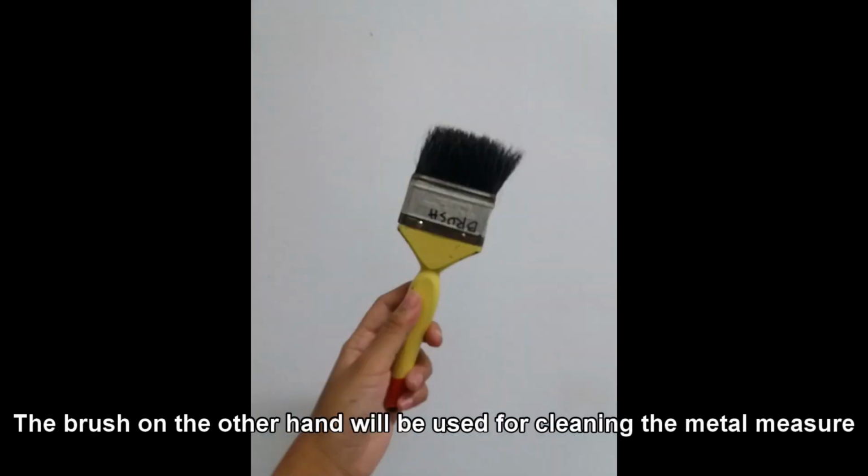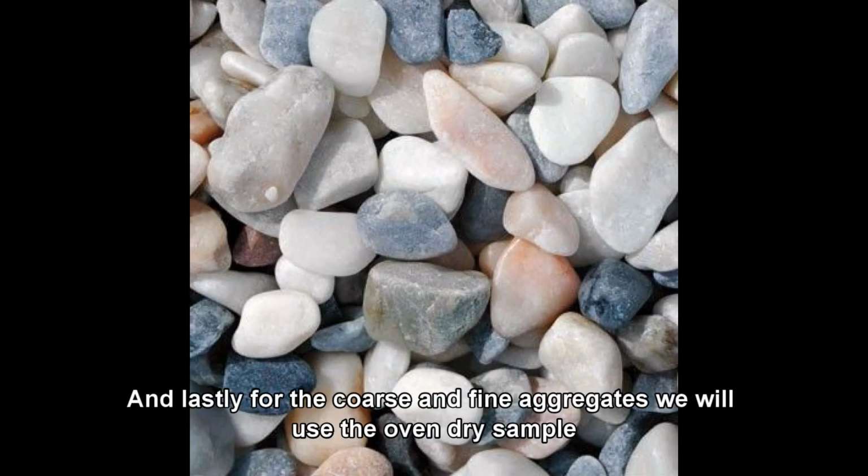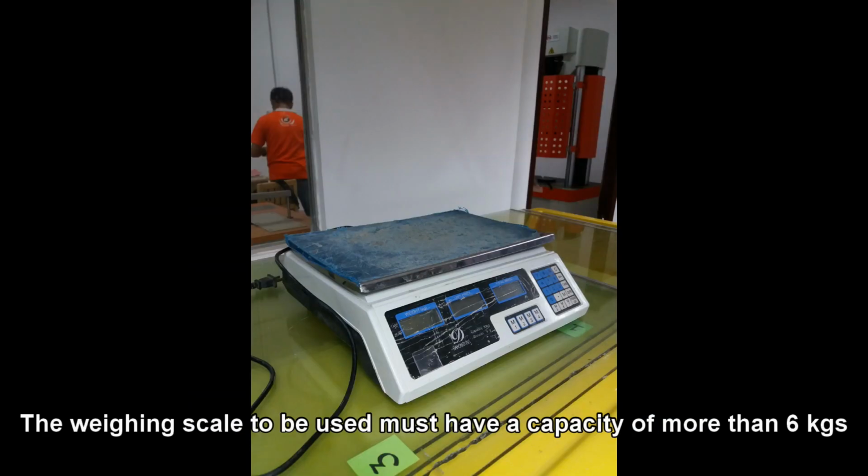The brush, on the other hand, will be used for cleaning the metal measure. And lastly, for the coarse and fine aggregates, we will use the oven dry sample. The weighing scale to be used must have a capacity of more than 6 kilograms.